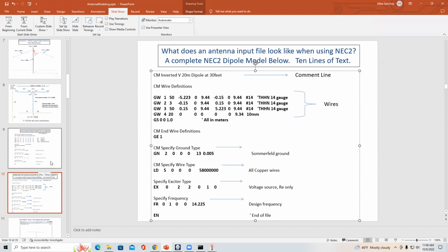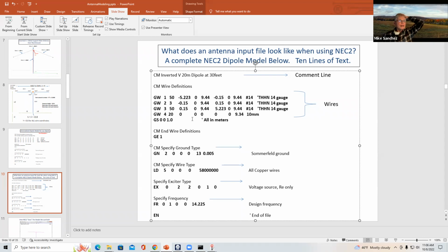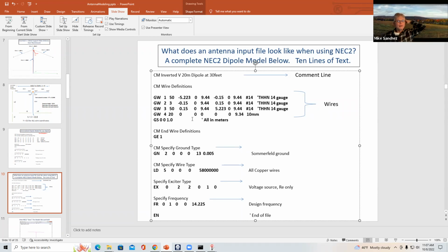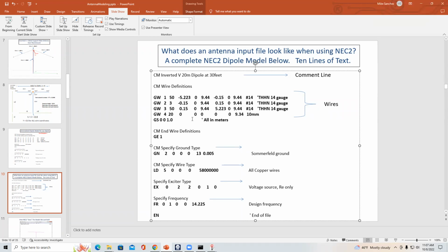I guess the question is, if you figure out the quarter dipole length, not including the center, is that the real quarter dipole, or do you have to consider half the center part of the dipole as well? Good question. When you use 468 divided by 14, that's the total length of the antenna. So that's a half wavelength. That's the total length of the antenna we're going to use.